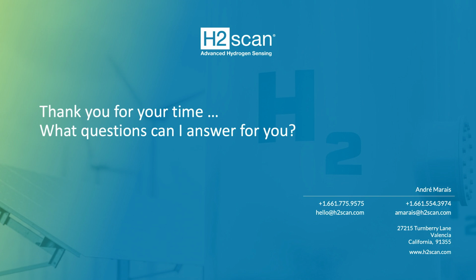Great. So, a similar question. Philippe asks, are the H2 values from online monitoring comparable to typical DGA values? For example, if DGA presents 10 parts per million on a specific day, should the average H2 value from online monitoring also be near 10 parts per million? Yes, it would. I'm assuming a few things. First, it assumes you take your samples from the same place at the same time. If you take one sample from the top and one from the bottom, you might see some variations, especially if your transformer hasn't reached equilibrium.